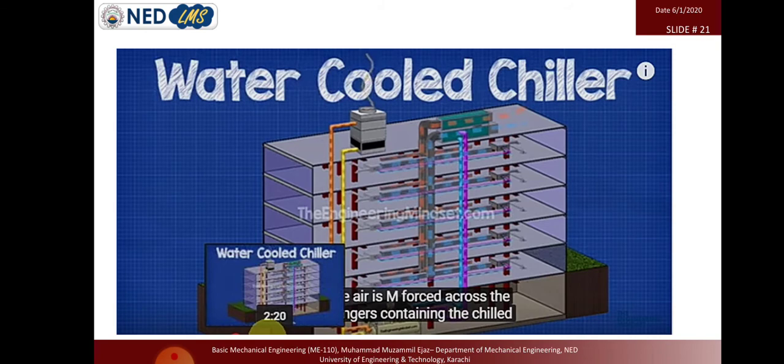Water has a high heat transfer coefficient, h value. So the condenser of the refrigerator or chiller is cooled by water. Similarly, the evaporator transfers cooling into the water. The condenser also transfers heat into the water, because water has more capacity for absorbing.